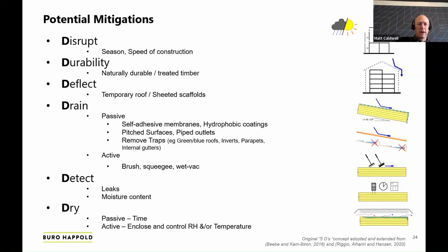The next D that I've added in there is detection. So that probably covers everything that allows you to know that you've got water somewhere. That could just be visual, to be honest. That could be walking the site and looking for wet patches. It could be digital leak detection or digital measurements of moisture content in the timber.